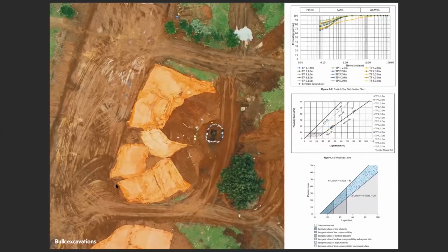Well, to talk about earthbags, we need to first understand the earth. And the earth here that we use for any earth construction must be earth that is extracted from below the surface. So it must be free from roots, free from compost, free from humus, and free from all matter that is really not earth.